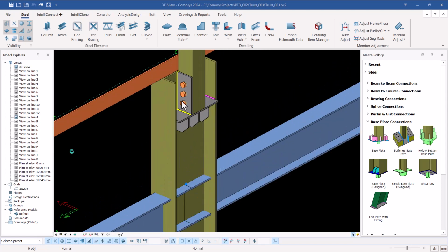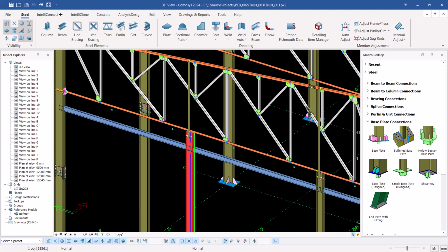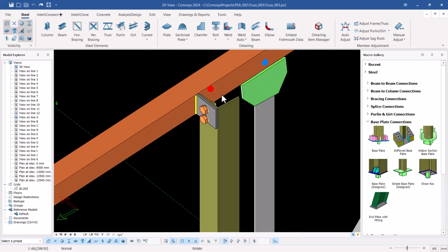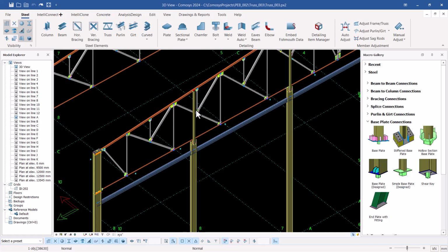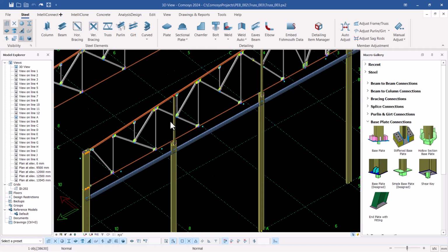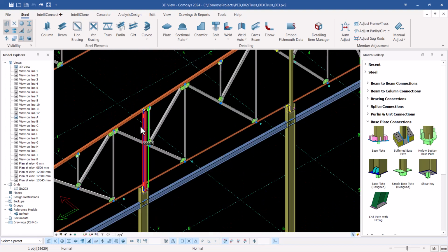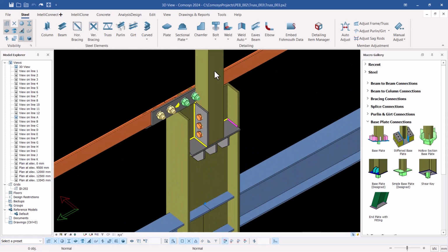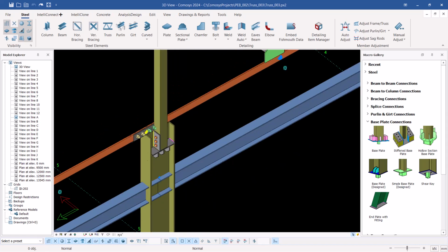So you can see at the gable side here, I tried to add gable columns and a bit of extension from the top end here all the way to connecting to my top chord here. This will help when you get to stages where we want to start placement of purlins or guards on the gable side. We'll find a space for connecting the purlins here. So that's why I've extended that, and I did the same thing here. And you can see the connection between this member and this frame here. It's as simple as that.